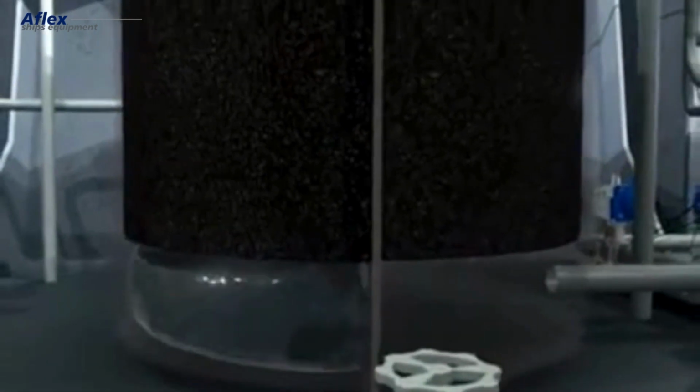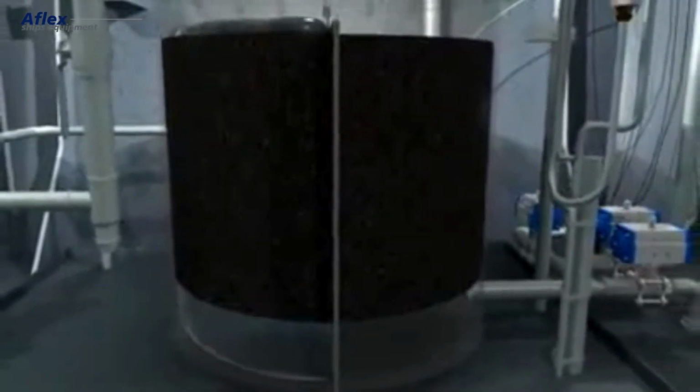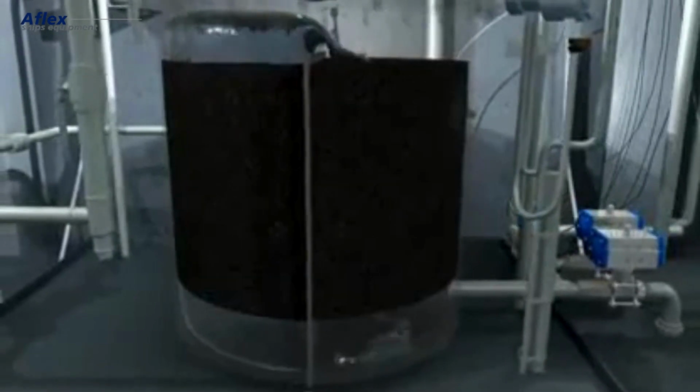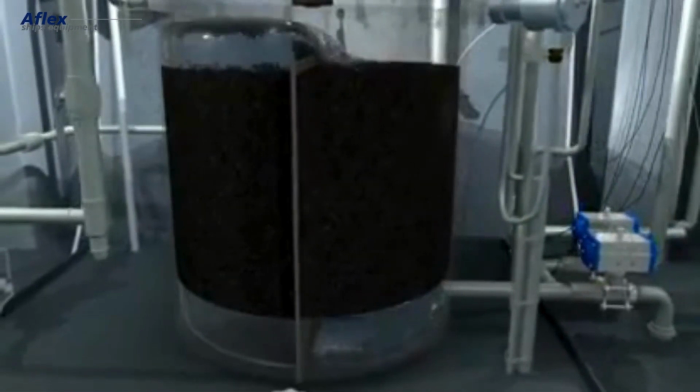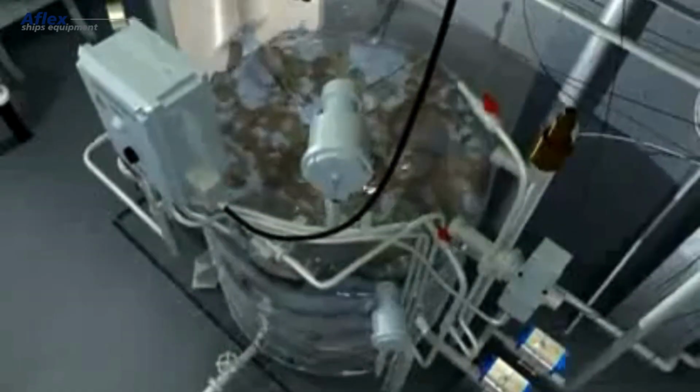At about half level, the liquid enters into the main OWS chamber. This liquid, as it fills up the main OWS chamber, also rises from the bottom into the first half of the coalescer filter. The liquid then flows over the solid partition down into the second half of the coalescer filter. The two coalescer filters are designed to trap the oil particles in the liquid.